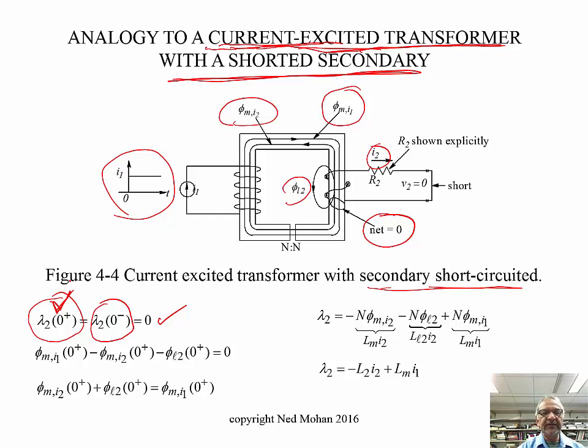So if you take this in the positive direction, and these two are in the negative direction with the negative sign, then the sum of all these three is equal to 0, and we can rewrite it in this fashion over here. So you see here that these are all linking n number of turns, and in this case we chose the number of turns to be the same, but of course they don't need to be the same.